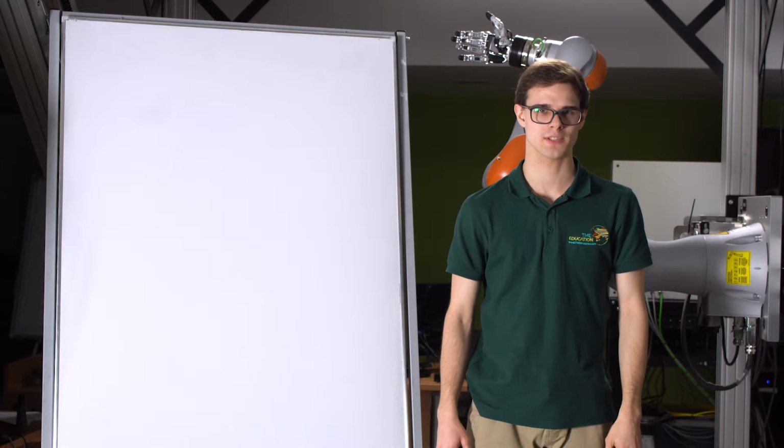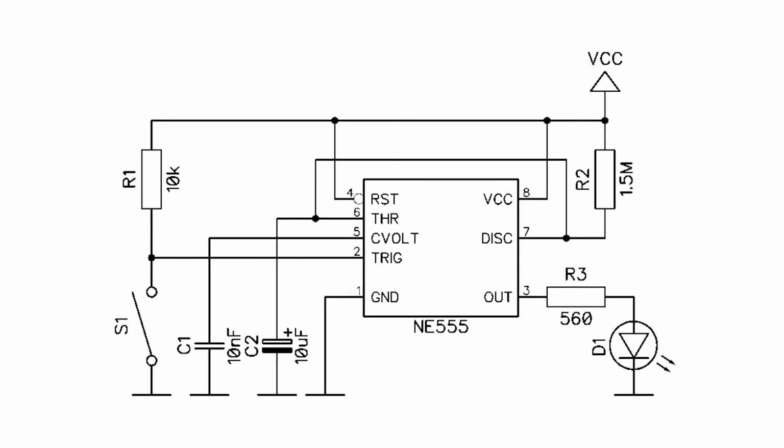Here we will talk about such a system implemented using the NE555 timer. The diagram shows a few small differences. In the stable state, the system has a high state at the trigger input. This is due to the fact that the inputs have such a high resistance that we can assume that the current does not affect them and R1 does not have a voltage drop. At the output, we have a low state and a switched off transistor.